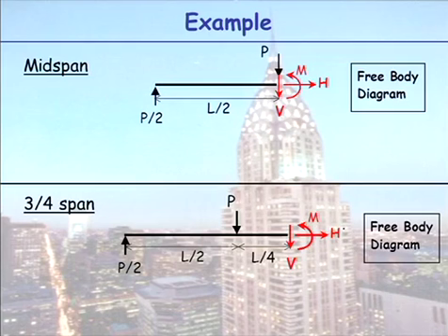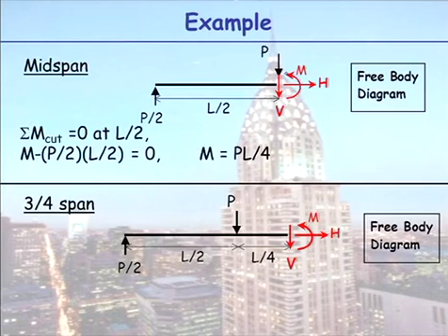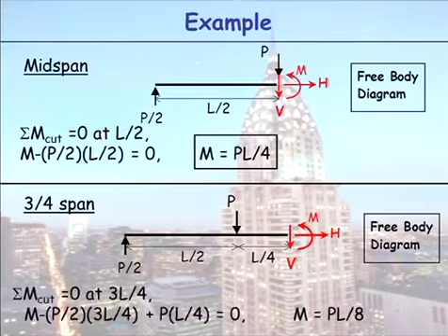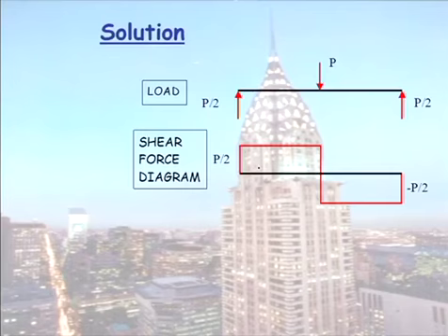Remember that. At mid-span, I want to know the value of the moment. I cut it at the mid-span. When it comes to taking moments here, I take moments at the mid-span, I get the value of my moment. I do the same thing at 3/4 span, I get the value of the moment. And now, shear force diagram, for this case, we've already drawn. We know what it looks like.